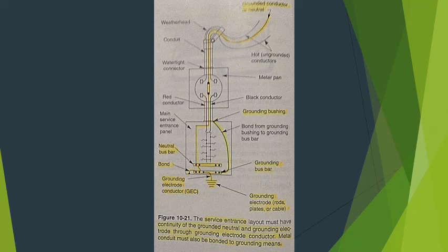Underground metal tanks or other such underground systems or structures. Rod or pipe electrodes that are at least 8 feet long, fully driven into the ground or buried no less than 4 feet below the surface.